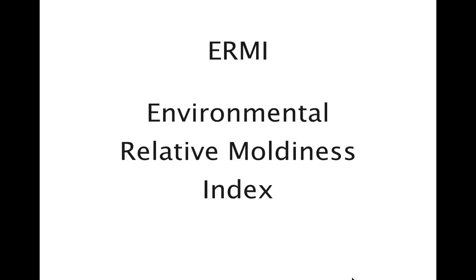Okay, the EPA actually has a test they call ERMI, Environmental Relative Moldiness Index. They have a device that you put on a vacuum cleaner, a simple vacuum cleaner a homeowner can do himself. You vacuum a certain area of highly trafficked carpeting or some other areas they recommend in your home. You send it to a lab, and the lab compares that to thousands and thousands of other homes that have also done this and rates it on a relative scale of percentiles. So, in other words, you could be in the 90th percentile of moldy homes, and say, "Oh man, maybe I have a problem here."